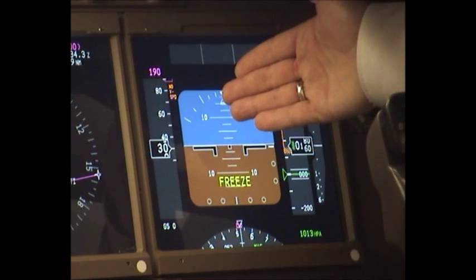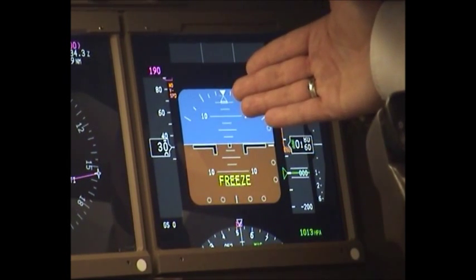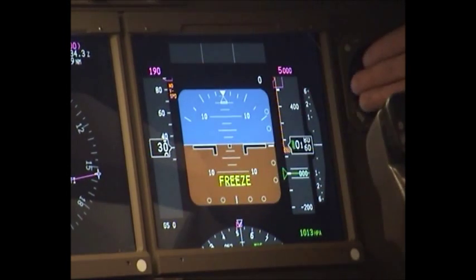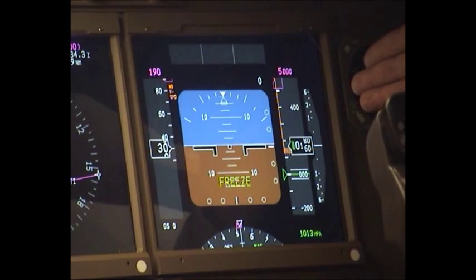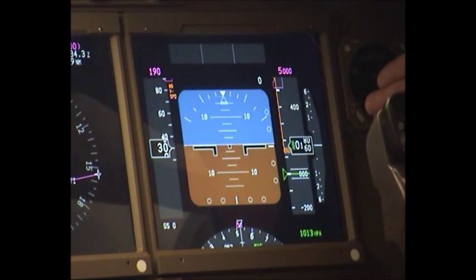On the left you see your speed, which is measured in knots or nautical miles per hour. You can see the ground speed below that. On the right you see your altitude, which is measured in feet. Further right you see the vertical speed indicator, which measures if you climb or descend in 1000 feet per minute.